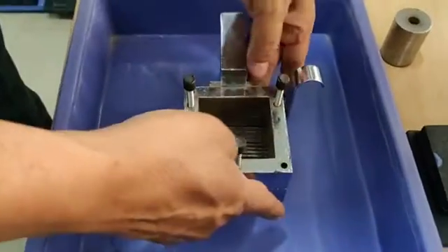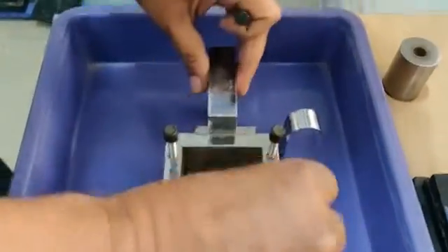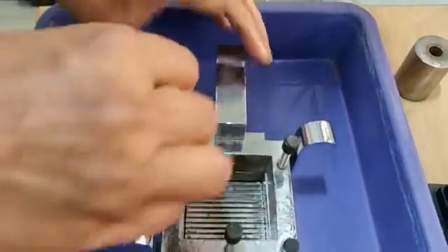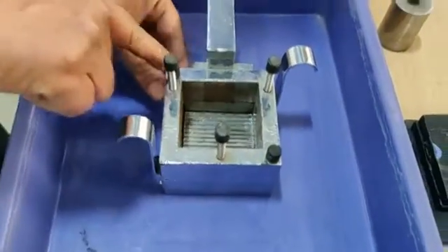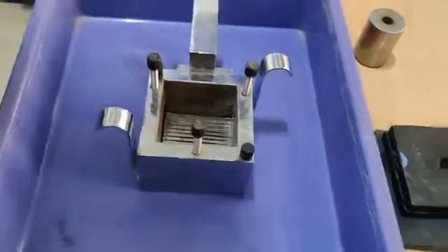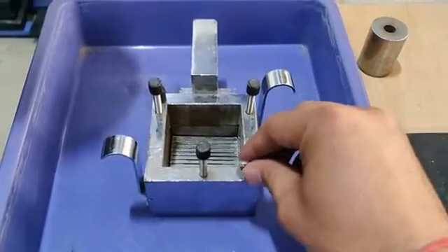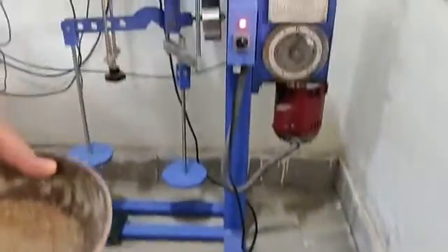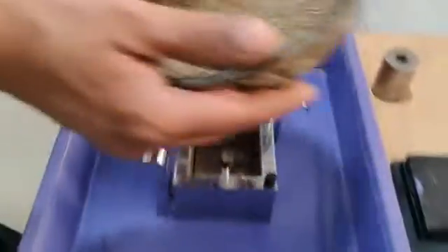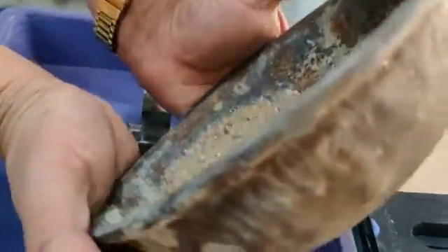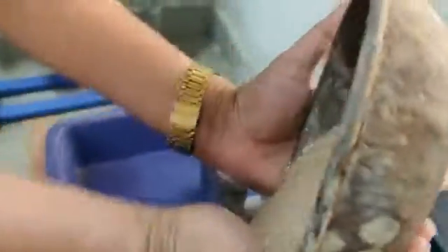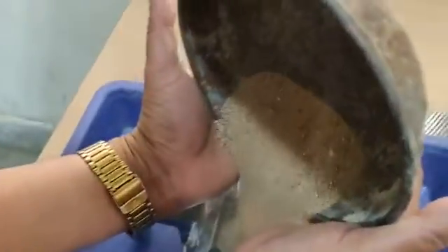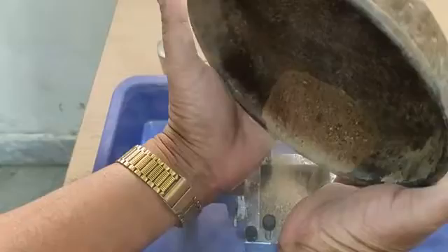This is how we are going to put the whole assembly together, and this is the soil we have taken. Two plates we have placed at the bottom of this box, and we have placed these two pins so that this will not move till we place this box in that box. Okay, now we are going to fill the sample into this box. We have approximately 180 gram of sand.